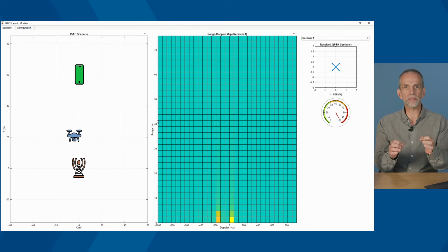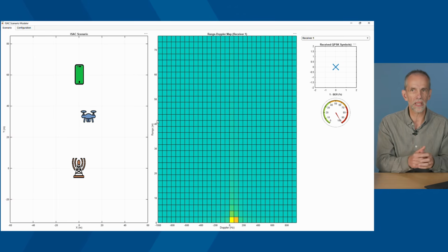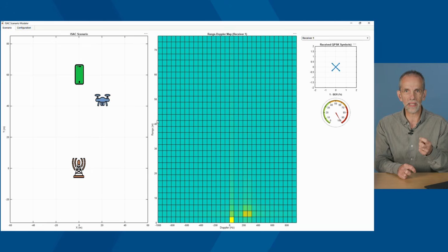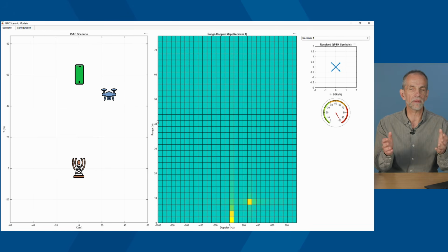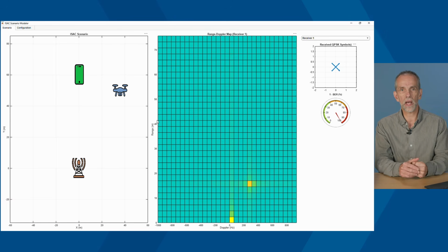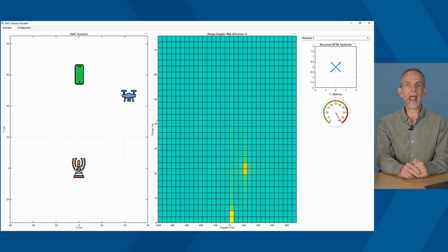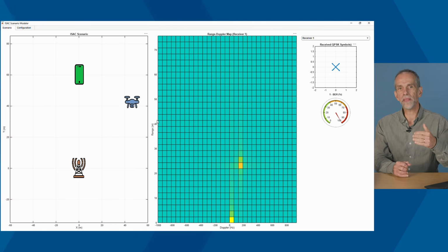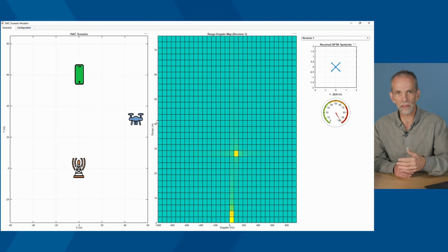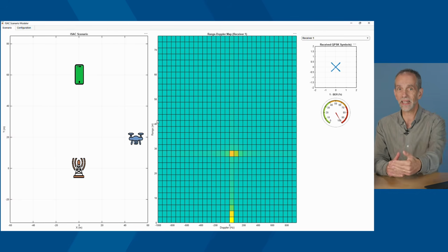So what happens, and now I'm going to flip between communication speak and radar speak, is that these channel estimates are being generated by the pilot signals, in 5G speak the DMRS signals, and then they're enabling a channel estimate in the frequency domain. These channel estimates are made over a periodic series of sequences, and then they are essentially concatenated in time.